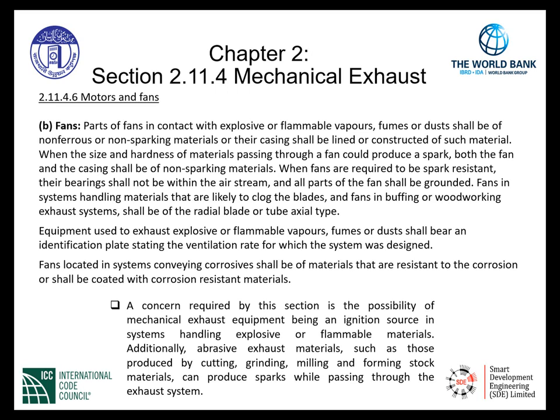Very important here that the system must be designed to convey at an airflow rate to exhaust properly the flammable vapors, fumes, and dust, and thus this requirement provides an identification plate stating the ventilation rate as such.